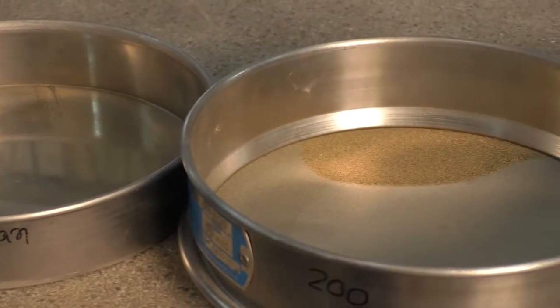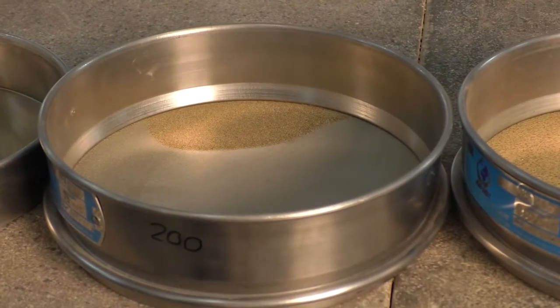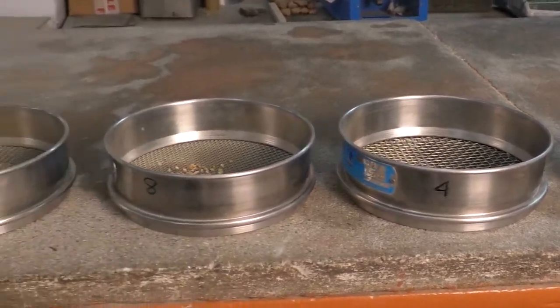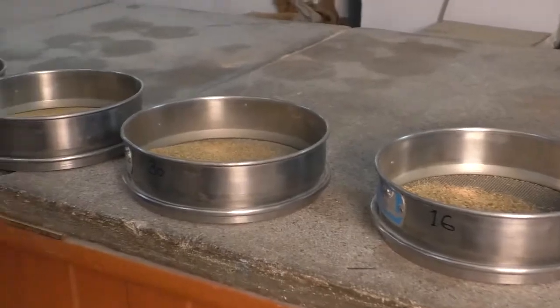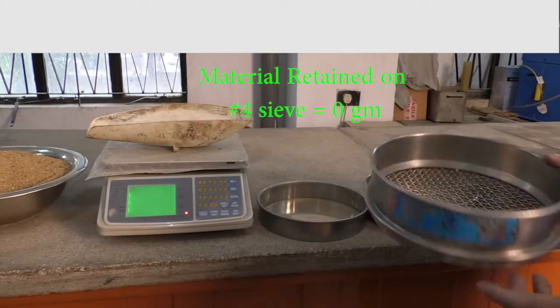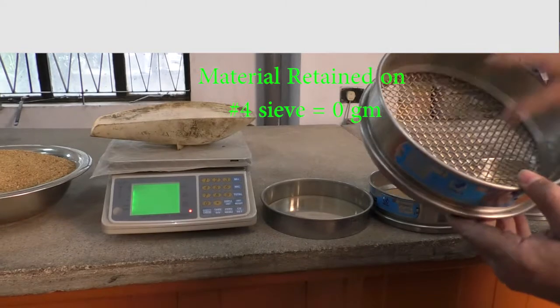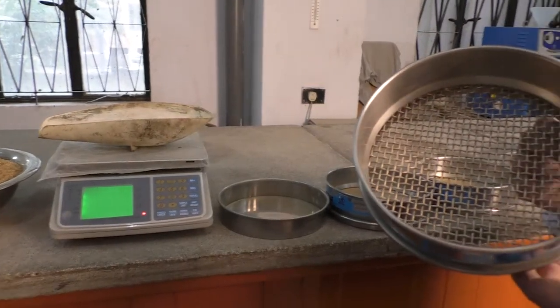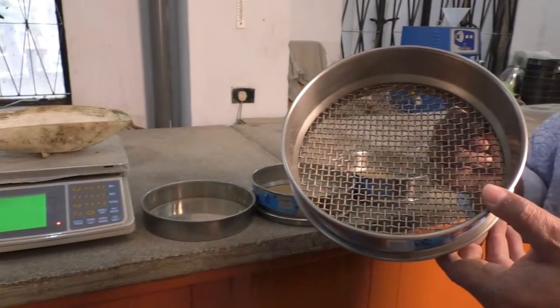It can now be observed that different amounts of the whole sample have been retained on these individual sieves. Next, we will measure the weights of the materials retained in each sieve. Since this is a fine aggregate sample, no material was found to be retained on the number 4 sieve, which indicates that all the particles of the sample are smaller than the opening of the number 4 sieve.